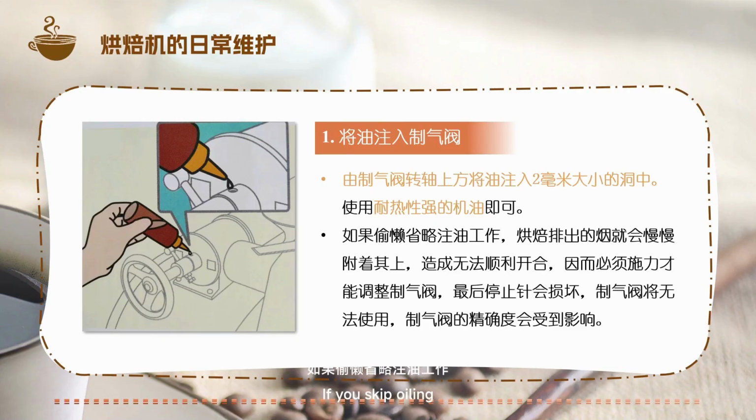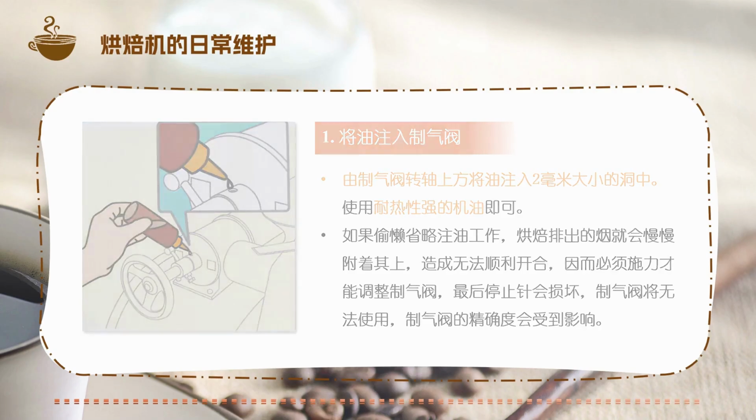If you skip oiling, roasting smoke will gradually accumulate, causing the valve to malfunction, requiring excessive force to adjust, eventually damaging the damper valve, rendering it unusable. Damper valve precision effects.